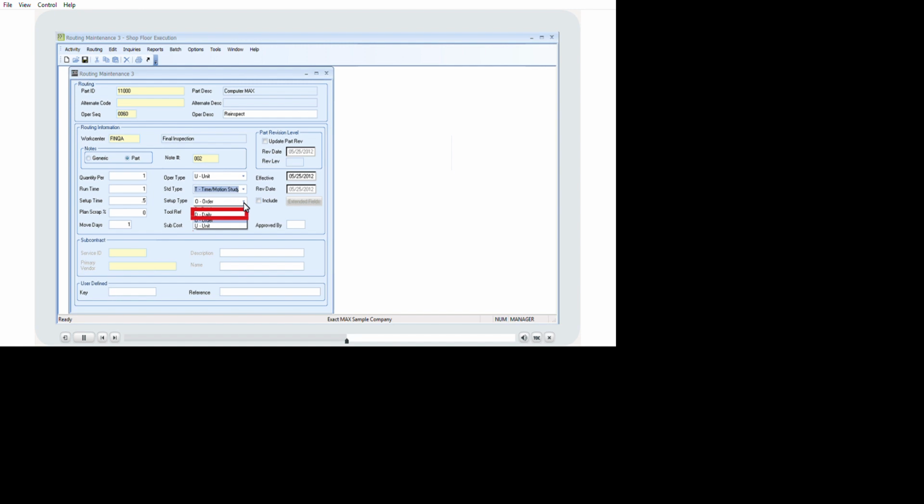If there are 12 manned hours per day at the work center, it will take 1.5 days to complete the operation, which is 18 divided by 12. If planned setup time is 0.5 hours, total setup time for this operation is 1 hour, or 2 times 0.5. Because it will take more than 1 day to complete the operation, that is 2 setup days.